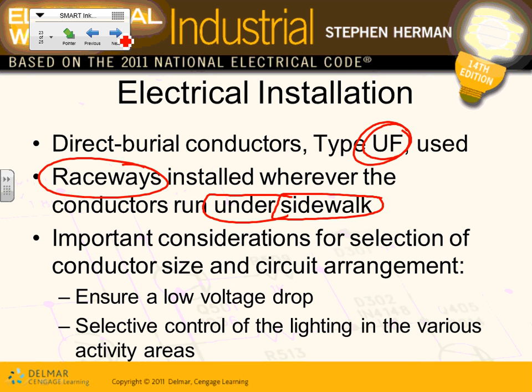But then you have to put conduits under every sidewalk, or like we did in our project when you guys designed it, we put what, 3/4 of an inch or half an inch? No, 3/4 of an inch or an inch, 1 inch conduit between all the fixtures, and we'll pull the wire. So two options. Why cable? Cable is cheaper.